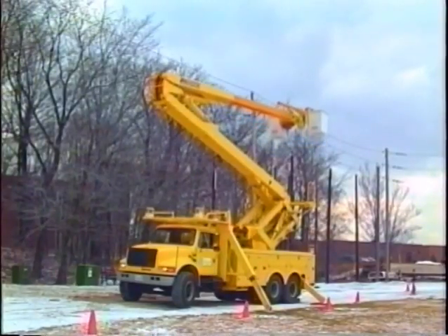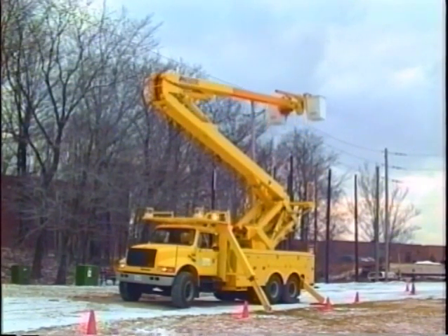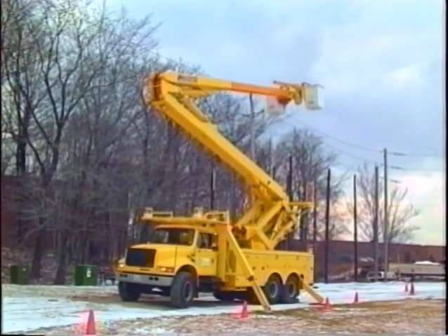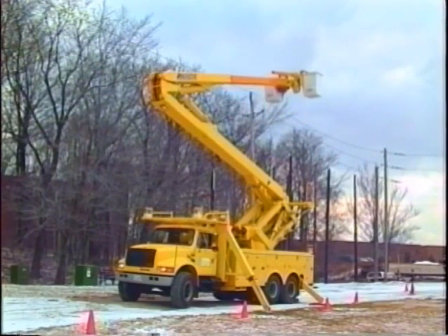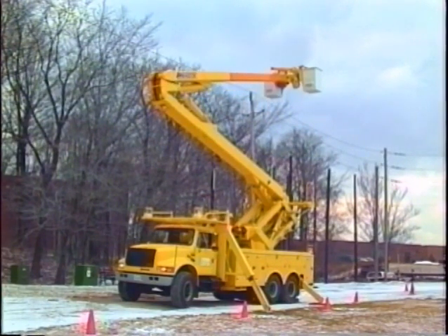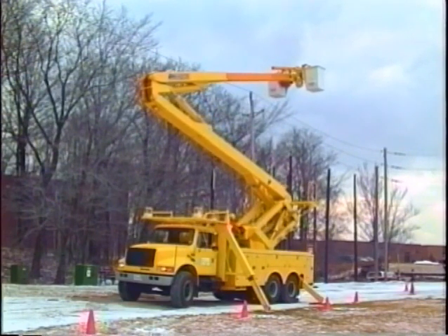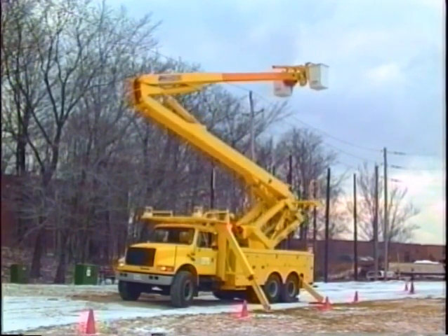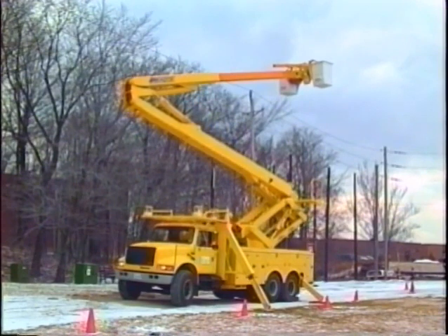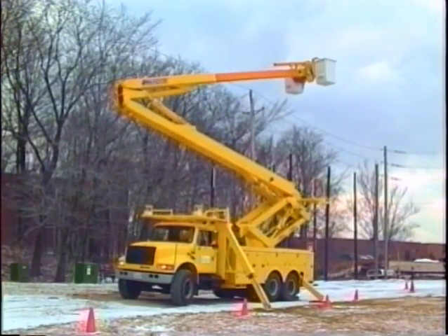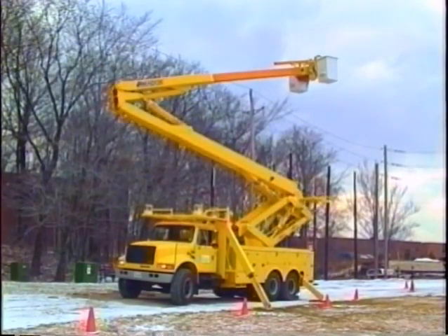After checking the outriggers, restart the engine if necessary and put the hydraulic system through its paces. What you are doing now is purging the system, getting rid of any air, and freeing up the check balls in the holding valves. Now, check the holding valves on the boom cylinders, in the same way as you tested the outriggers.